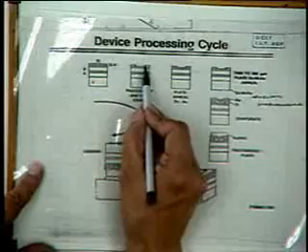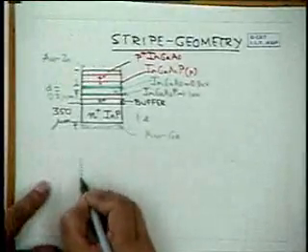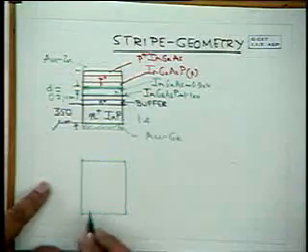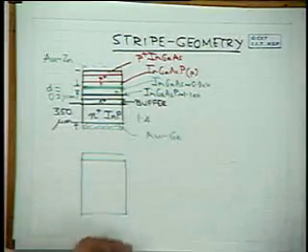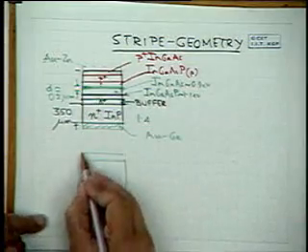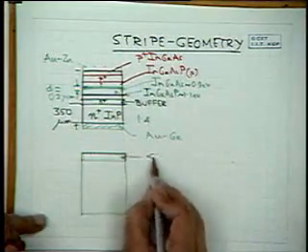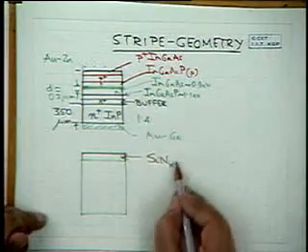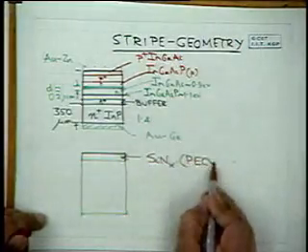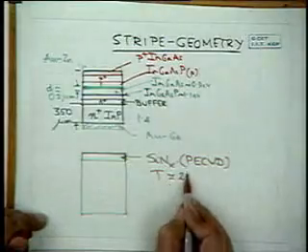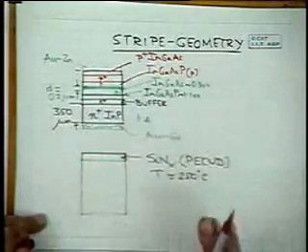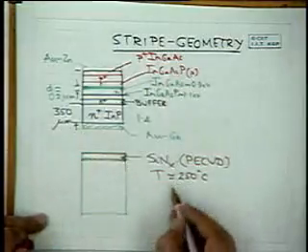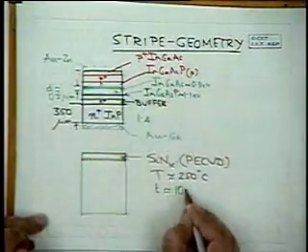We want to define this stripe. Okay, so what do we do? On this substrate with the grown layers, we grow silicon nitride, typically by plasma CVD, so that the temperature of growth is reasonably low, something like 250 degrees centigrade. Why? Because you do not want the device structure to be exposed to high temperatures. You will get interdiffusion. You do want to avoid interdiffusion. This may be a thickness of the order of about 1,000 angstroms or so.